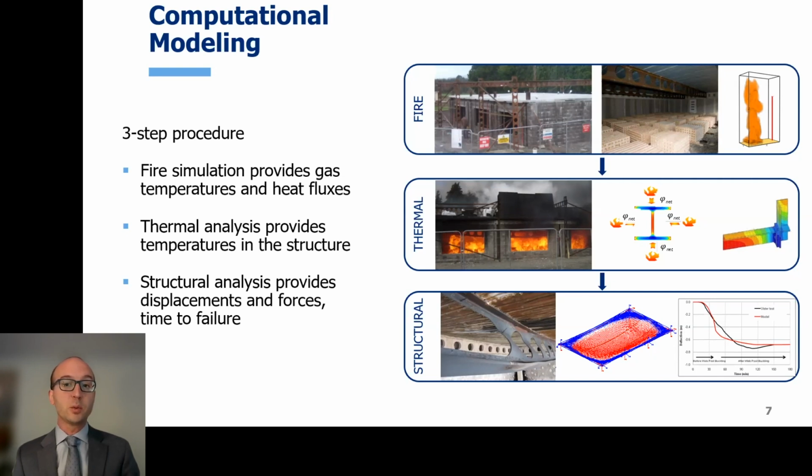Now, how does that work if we want to assess the fire response of structures? Well, it is a three-step procedure. First, we need a model for the fire development. We need a fire simulation that will output gas temperatures, heat fluxes, radiation, radiant intensities, and so on to find out the thermal exposure of our structural members.